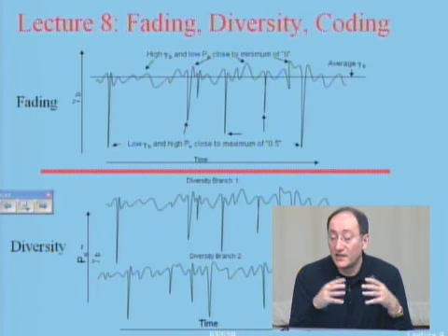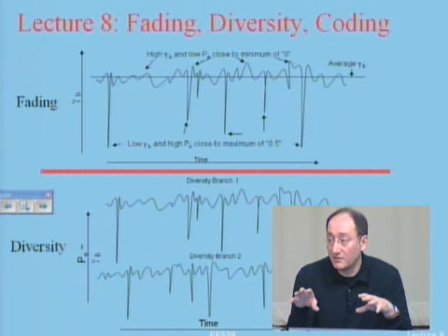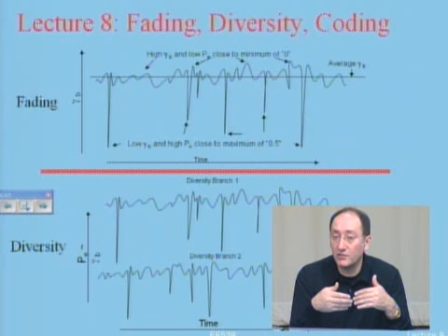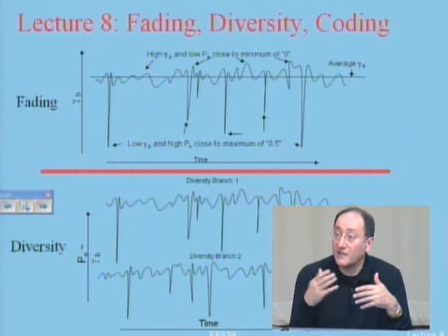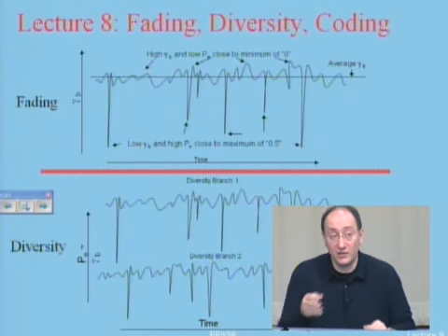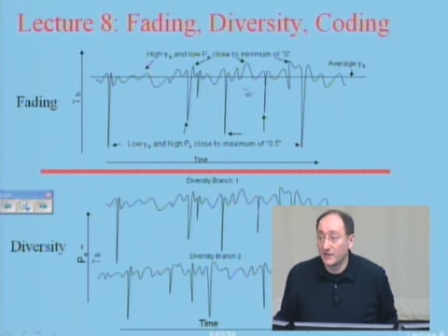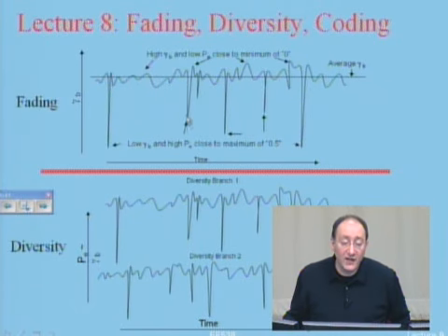But anyways, the raw data that I have, I can never eliminate the error rate. If I want more secure communication, I will have error correction codes and retransmissions. This is what they do for radio, for wherever you are. Okay, but we are talking about only raw data. And for raw data, in these areas, I have error rates like 10 to the minus 2, 10 to the minus 5. But when I have fade, I have error rate of 10 to the minus 2.